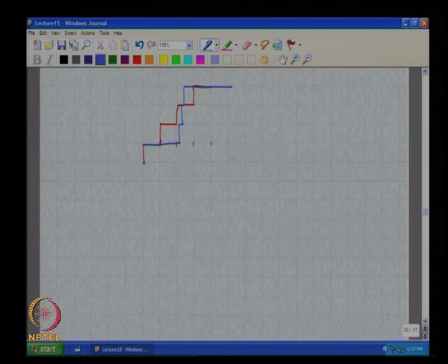You understand? So what is the DNL corresponding to this code? +1, right? And what is happening to this guy? It is not -1, but it is close. Similarly, so is this and so on, right? Because if the DNL exceeds +1 LSB, it does not mean anything, right?